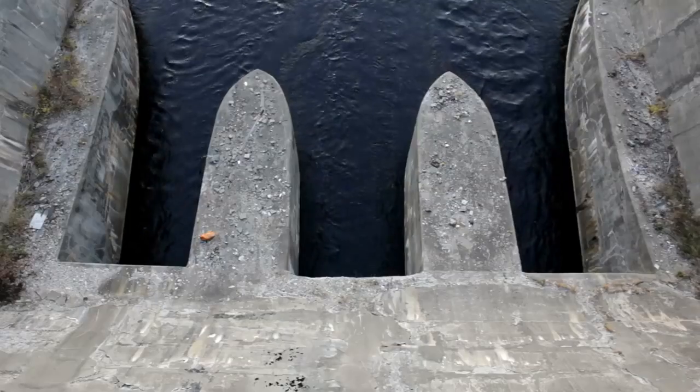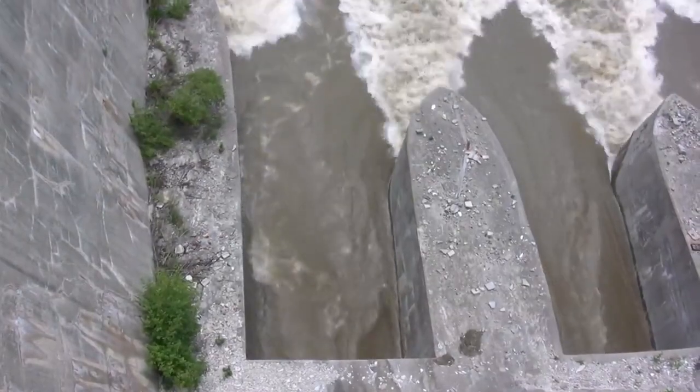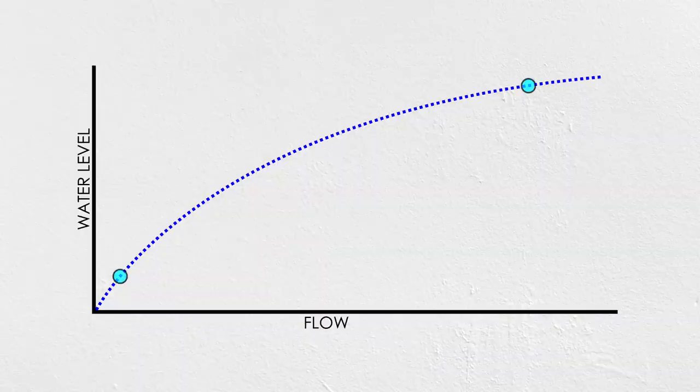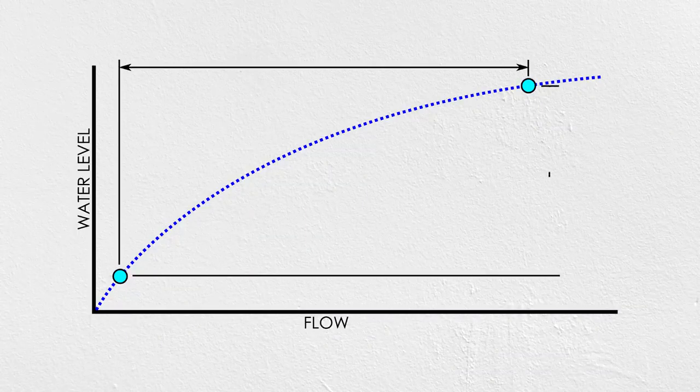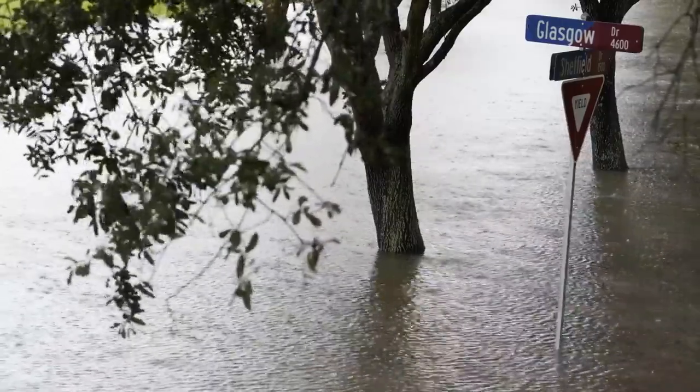Streams and rivers are subject to tremendous variability in flow rate. A hydraulic structure may normally flow a small amount, but in flooding conditions be asked to pass incredible volumes of water. With a passive structure and fixed rating curve, that variability in flow means tremendous variability in the water level upstream. During a flood, a weir may back up water badly enough to cause damage upstream.